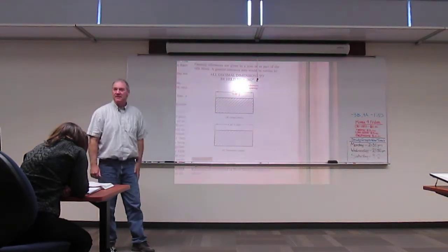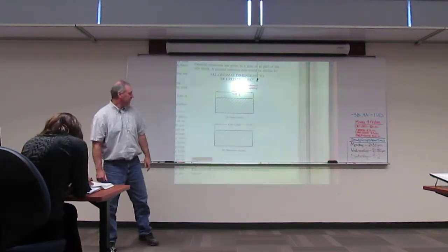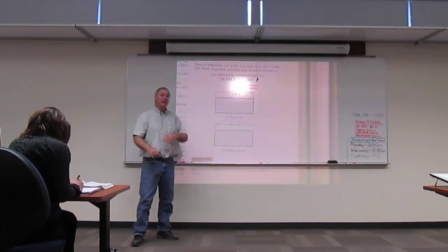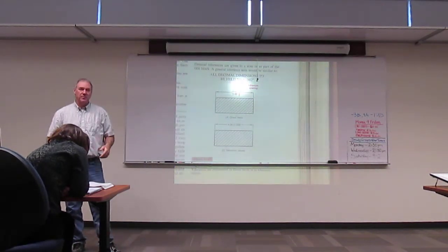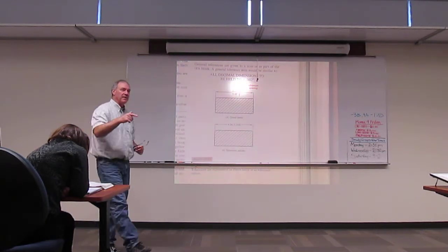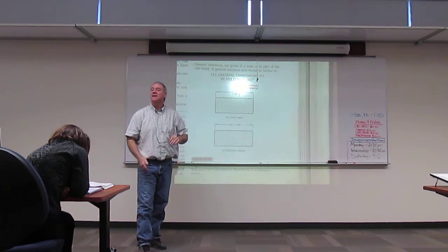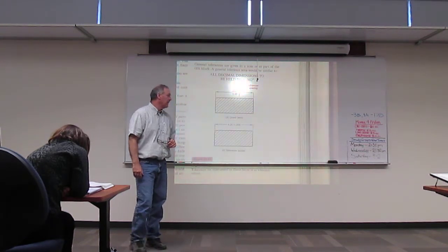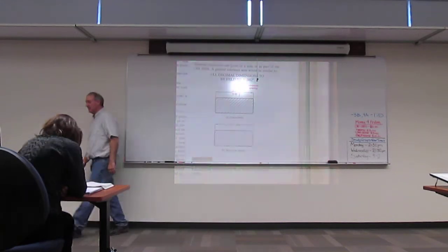But the point being on this drawing is that you can allow it to where it goes. Now, if you use a plus minus, they can go upper and lower. Tell them we want it at 4, but you can go 4.003, you can go 3.997. And anything in that zone is acceptable. So direct tolerancing, applying the tolerance to the dimension itself.